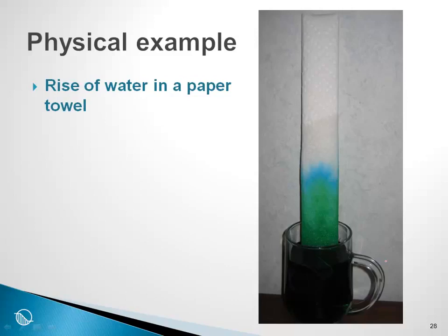What is interesting here is that we can make some assumptions about the property of the paper towel, and we can simulate this phenomenon with SEEP-W. So it is obvious that we have a zone here that is much darker, and you all know that this is often called the capillary zone.